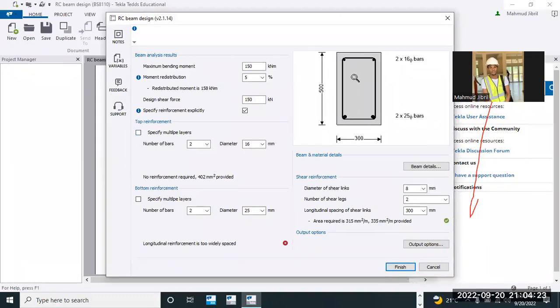So after this, what am I going to do at the bottom span reinforcement? You as a structural engineer will know that a certain moment requires a certain number of reinforcement bars at the midspan of such a beam. For 150, I know if I go with Y16, it will go almost up to 6Y16 because it is a rectangular section, not a flange section.